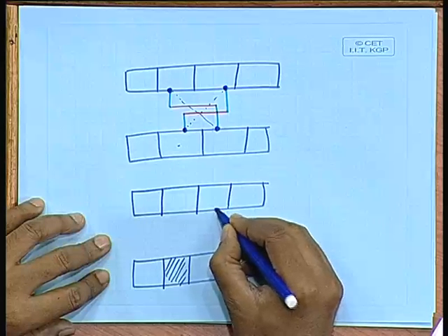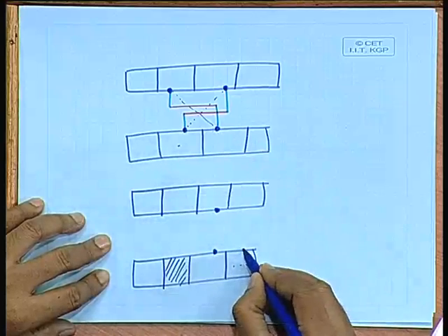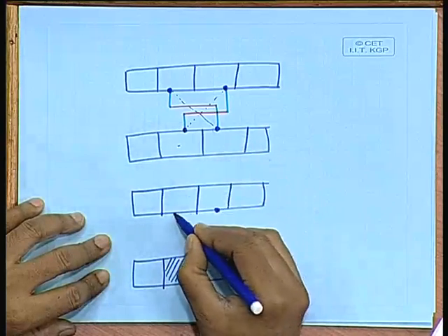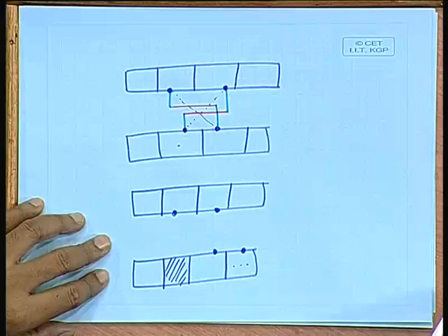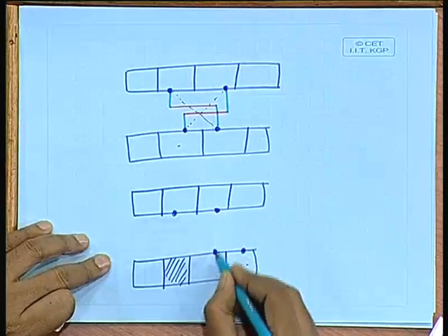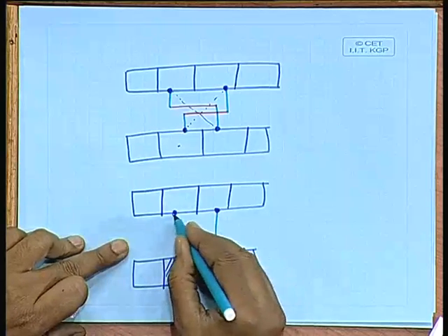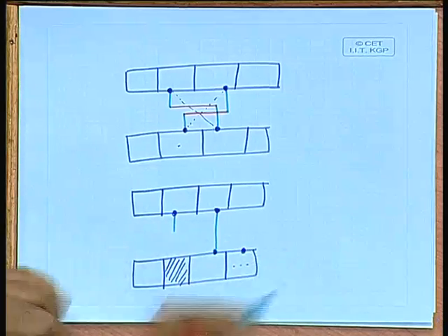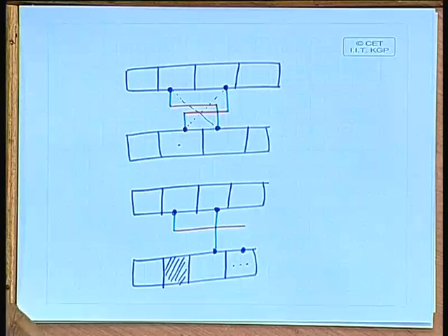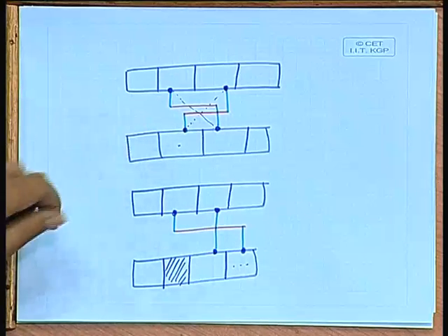Say this pin will be here, and exactly below it I will have this pin. The other pin will move further right, this pin will be here. So now the advantage again is that for this net, since they are vertically exactly one above the other, I can route them in the same layer, and I can route this in only one track. So I can reduce the number of tracks required for routing if I have a scenario like this.